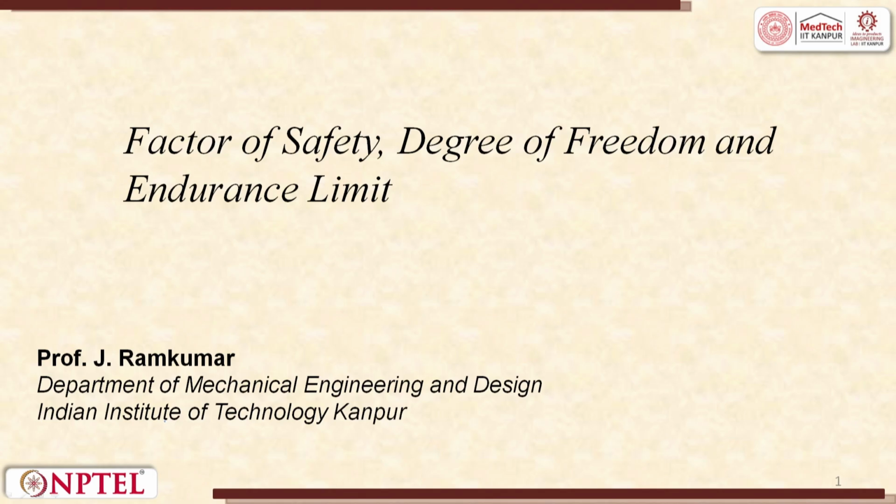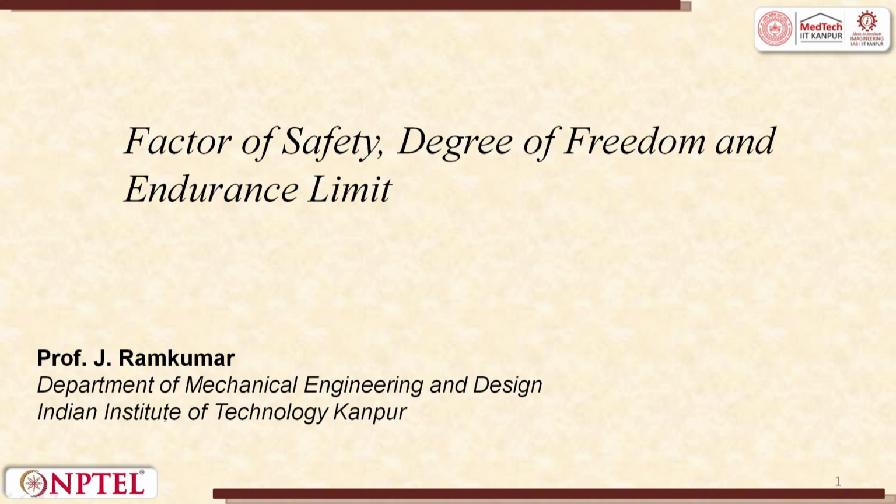Welcome to the next lecture on factor of safety, degree of freedom and endurance limit. This is very important because in engineering design, we always add a term called factor of safety. Factor of safety is something like a multiplication factor. We try to have 1.5 times, 1.9 times, 3 times, 5 times, 20 times, 30 times. When you construct a bridge, they have 30 times. In the automobile industry, it varies between 1.2 to 1.5 times. So, that is called factor of safety.